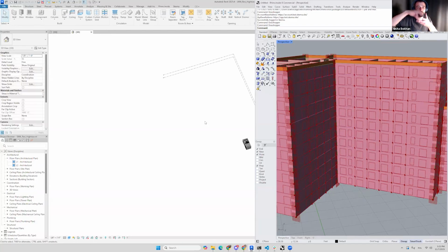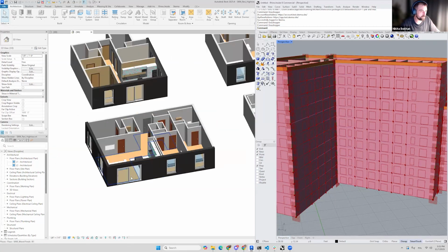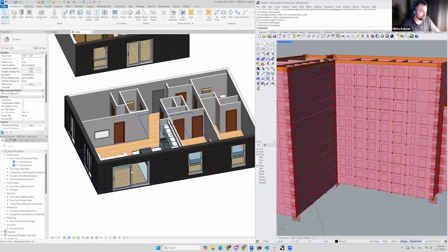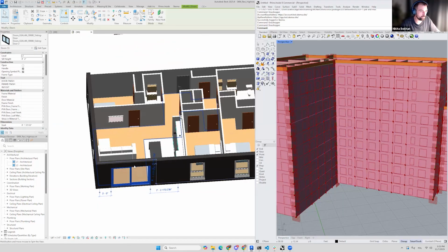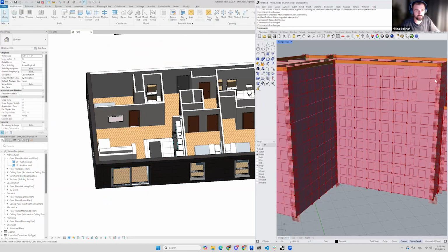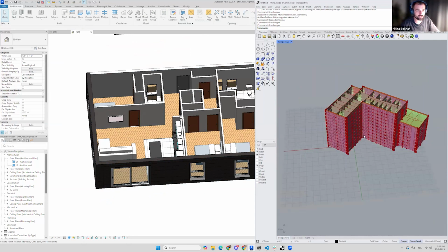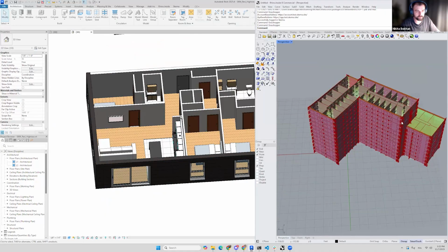I might want to replace all my walls, or replace the families. And here I can just receive the basic starting point of where the windows should be placed, what the width is, and so on and so on. All my windows are located on one wall, so they can easily be translated to Revit for Rhino.Inside.